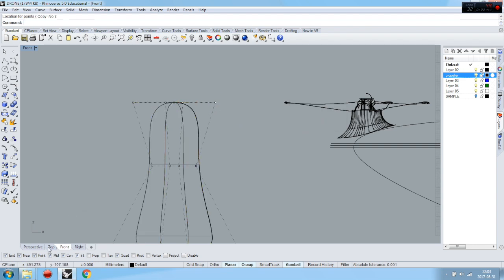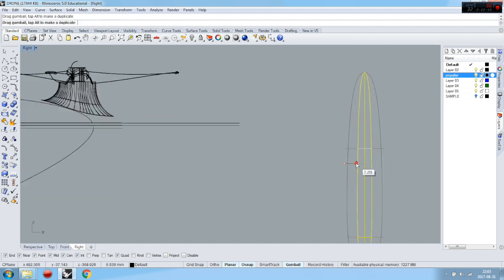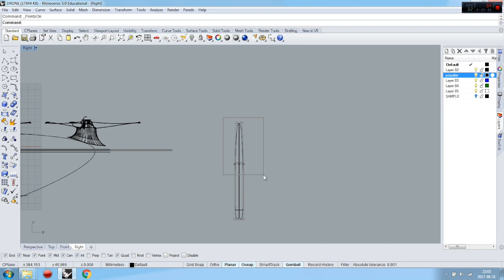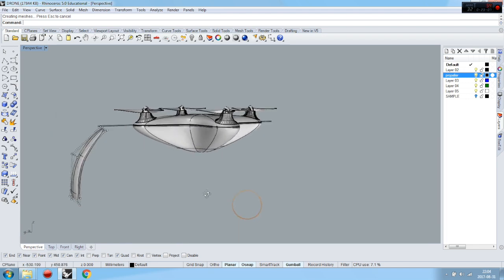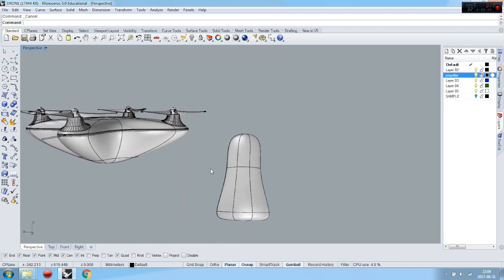And from the right view, I'm going to move this because I don't see anything. I will make it thinner, and then turn on control points with the left mouse button, and I can just scale it like that. And it's going to be the easiest way. Of course, remember, this is not the method to make these surfaces for, for example, injection molding. This is totally different. It's not beginner stuff. Doing anything for injection molding is very advanced. I've got a very simple leg.